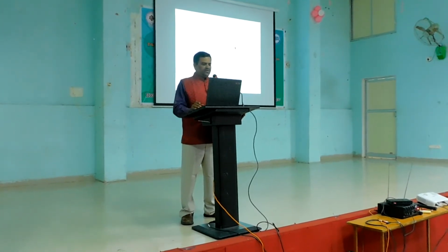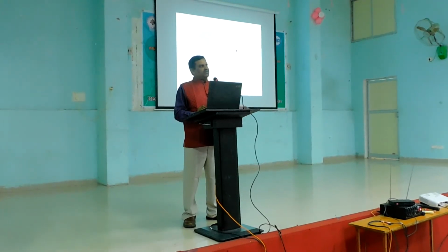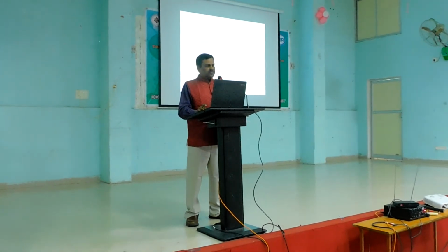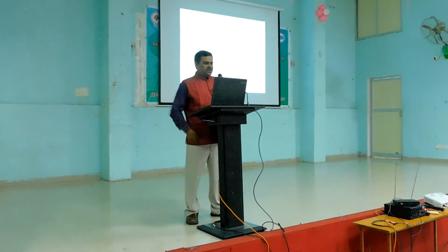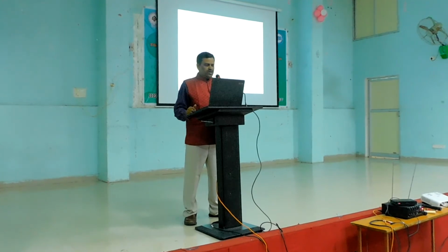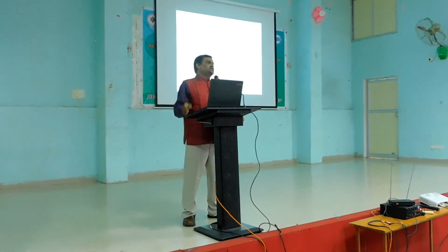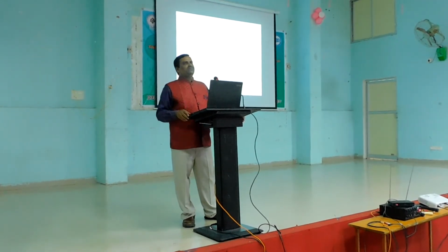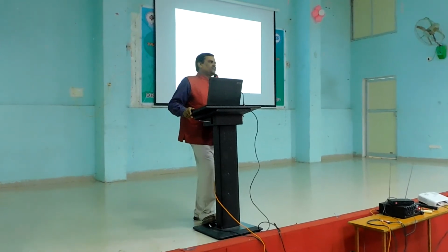Then with notch and without notch, you can also compare the 3-point bending or 2-point bending, etc. We can do the UTM test or impact tests, Charpy, Izod, etc. Now you see the material property, how the Young's modulus is changing with respect to aspect ratio. As you change the aspect ratio, the properties are changing. This is the peculiar thing which we take advantage of when we are using a nanomaterial. That is the simple terms of what I want to say.